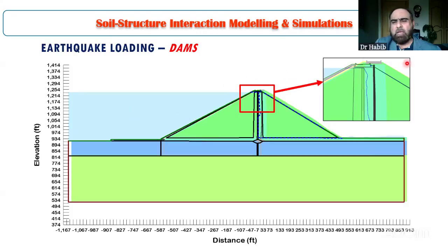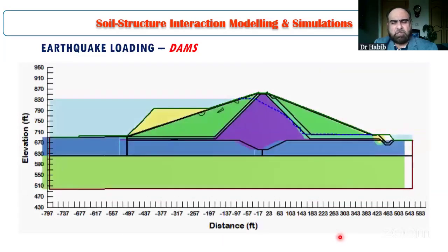But what we get from here, we can see here, we are interested in the total deformation, and not only total deformation, we are interested in the stresses, strains, pore pressure scenarios during the entire earthquake loading. So I can show you one simulation of that, how when we load the real seismogram on this dam, how its components are moving. It's a little bit exaggerated form of the movement, but this is how these move. And then the real pore pressures, stresses, and strains could be envisioned in this model.